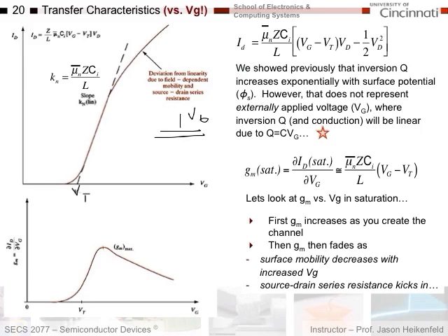So I've got VG here, and then I've got a channel down here. I apply my gate voltage out here, then the charge appearing across my gate capacitor should be calculated according to Q equals CV. And if the amount of charge I have in my channel determines the conductivity of the channel, then I should see my drain current go up proportional with gate voltage. More gate voltage, more charge in the channel, more current flow because the channel is becoming more conductive.